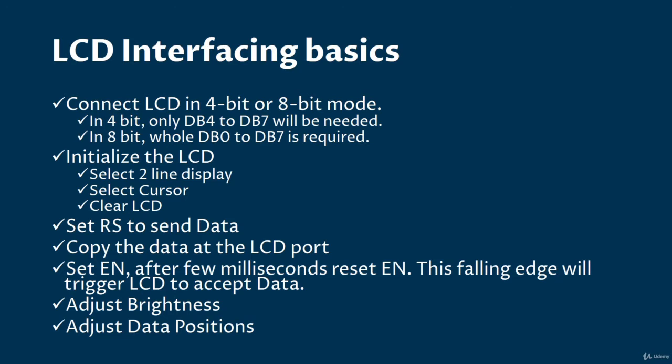For initializing, you have to send commands, like selecting the 2-line display. Then you have to select display on, cursor on, or display on, cursor off, anything. Then you can use clear LCD. By this command, the previous contents of the LCD will be cleared.